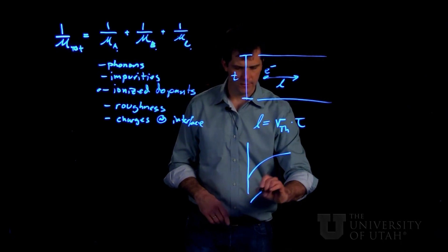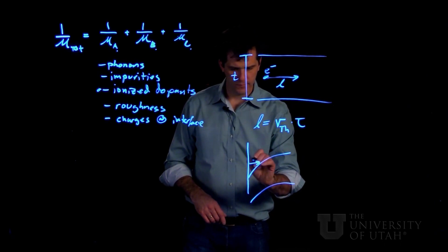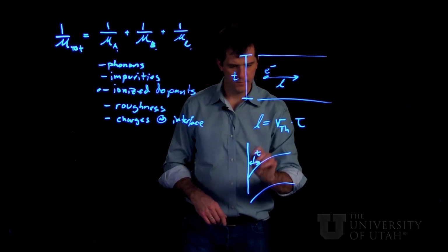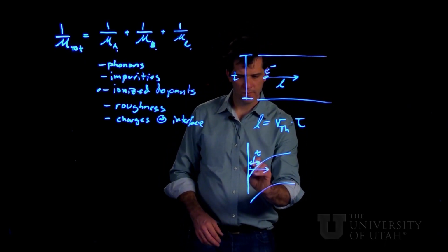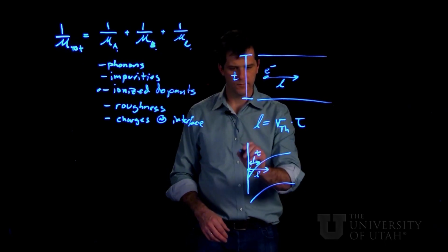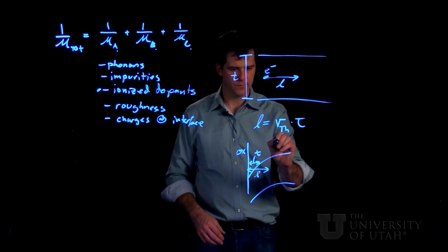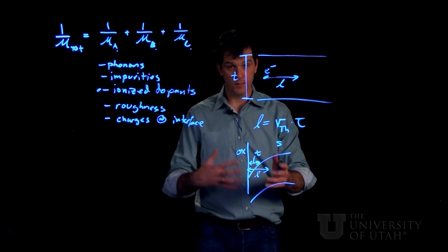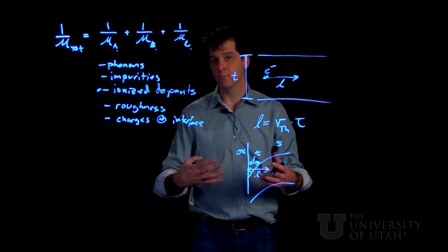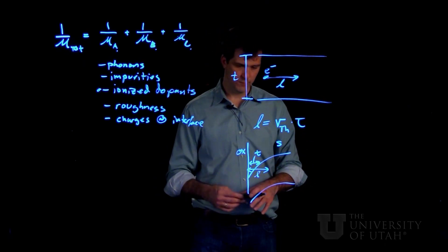So I'm talking about an effective distance here, t, and if the mean free path L is bigger. So I'm drawing here the oxide to semiconductor interface, including the band bending, for again our enhancement mode p-body MOSFET.